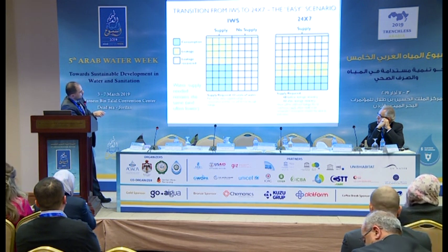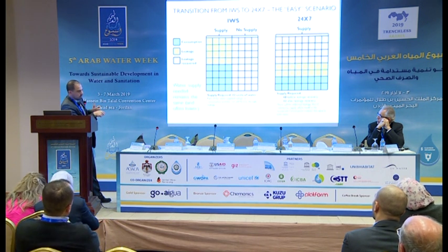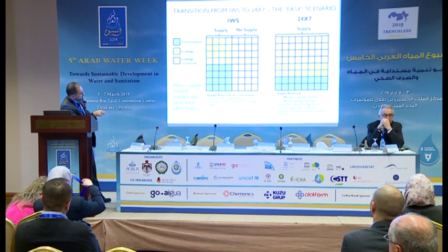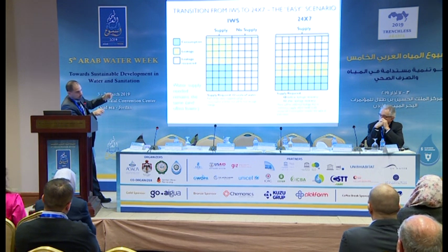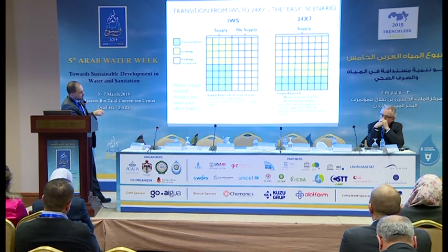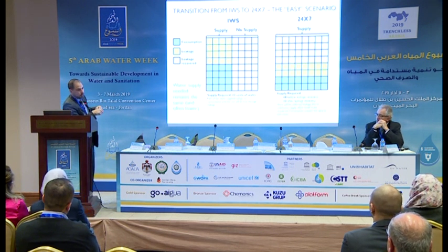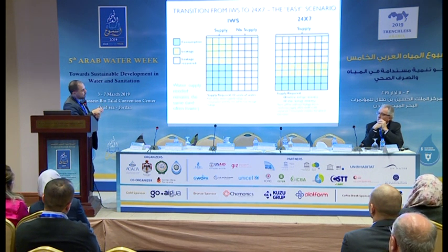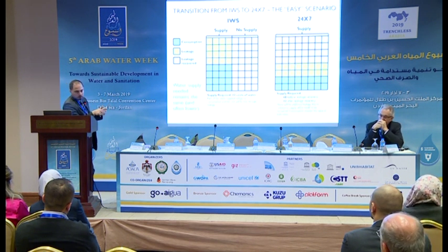So we are assuming here that the demand is met. So the blue color is the consumption delivered to the people. So we supply for 50% of the time. The quantity will be the total amount here, which is 32, for example, cubic meter or unit of water, which is both the blue and the orange. The orange will be the leakage, because we supply, we meet the demand, and the remaining under intermittent supply will be those. Now, for the remaining of the week, which is the 50% of the time, there will be no supply in the network.